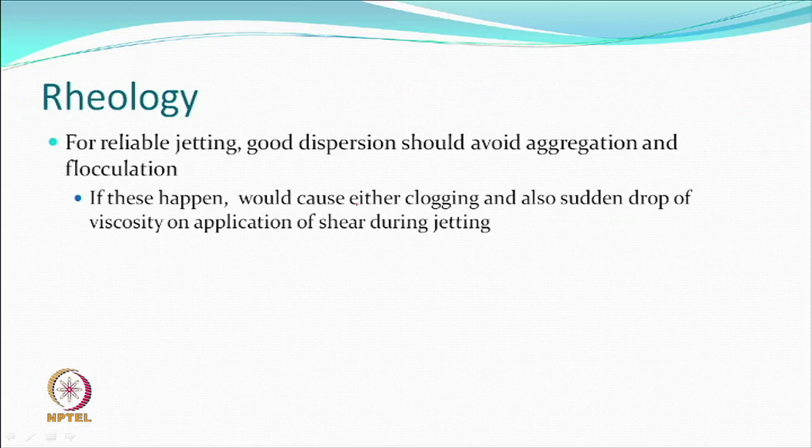For reliable jetting, the rheology, what happens when you put shear, would be important. Good dispersion definitely, so that no aggregation or flocculation takes place. If these things happen, then obviously clogging will happen, sudden drop of viscosity may be seen, particularly in the shear condition.